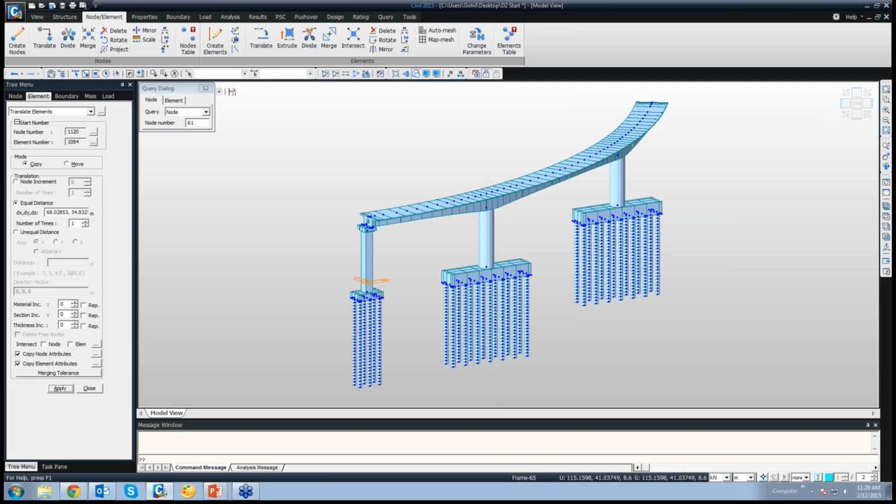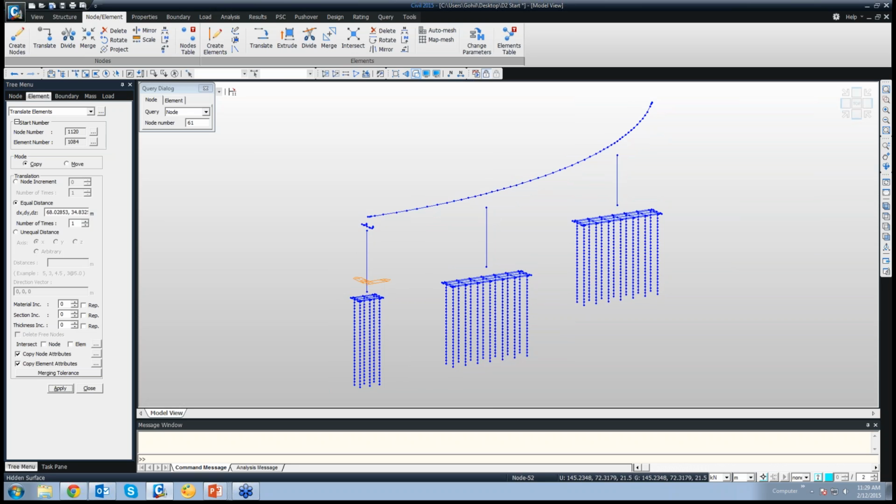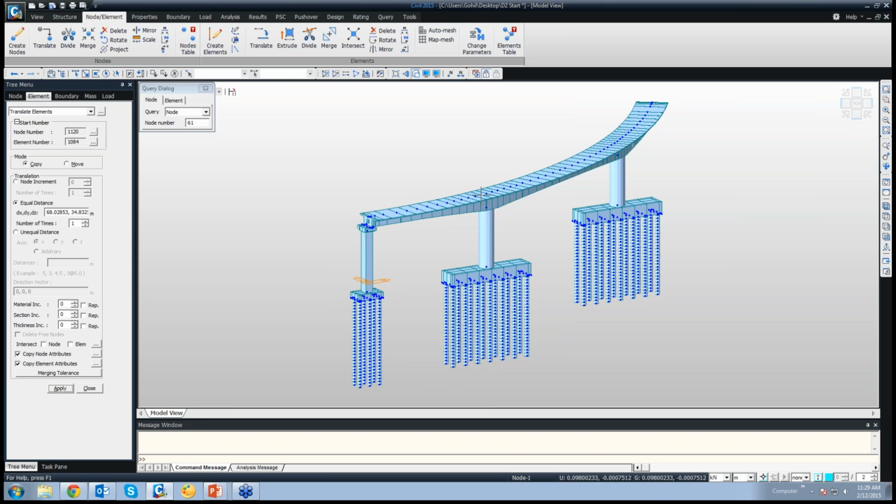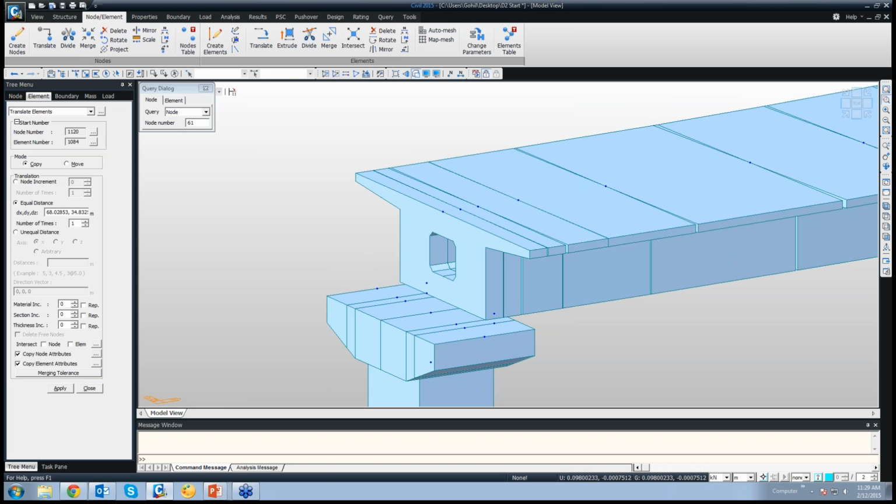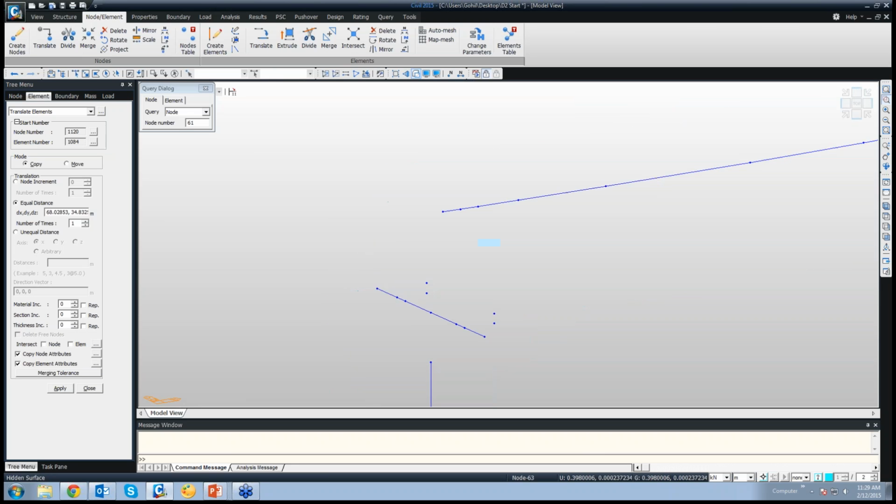Okay. So in this, we can see that it's a line element. These are the top of the box, the bottom of the box, but in reality, there is no connection between them. And it has been stated in codes that plane element remains plane. So it is basically a rigid body. So these have to be connected by a rigid link. Now, for a rigid link, it is assumed that a rigid link has very high stiffness and the distance between the connecting nodes remains constant if the rigid body option is used.